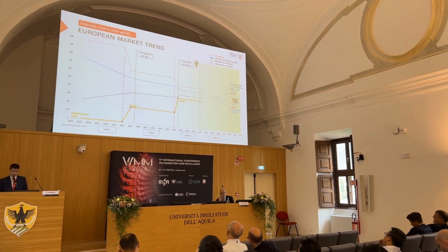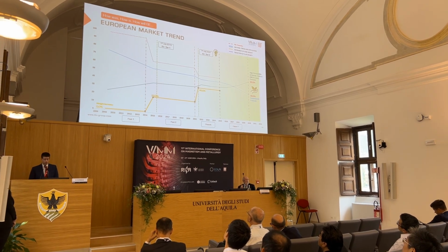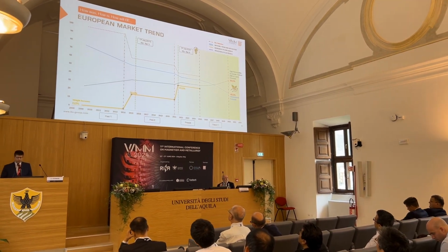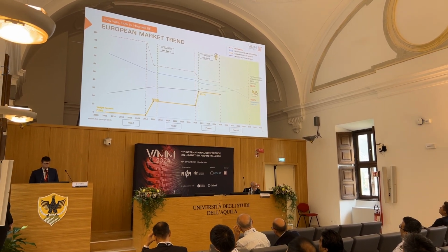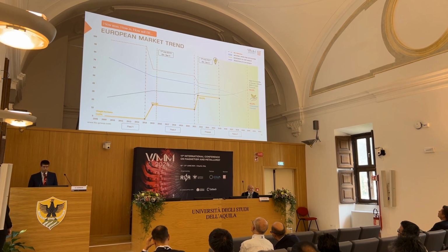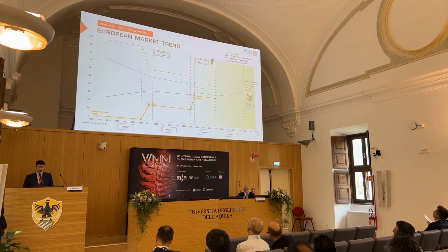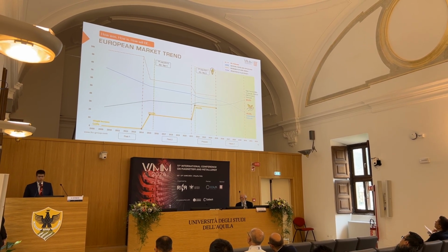Now we can see how the design will change and how it's changing over time to support the no-load loss reduction. In general, the TÜV regulation takes into account the no-load loss reduction, but how the customers are achieving the reduction of the losses is by making changes in the design, and we can see a core weight increment of 20% in each step.